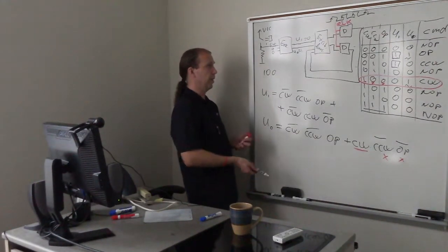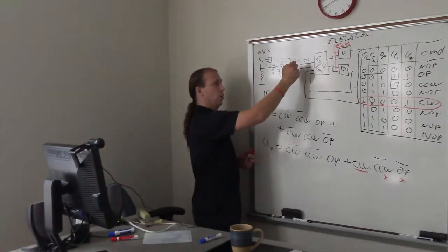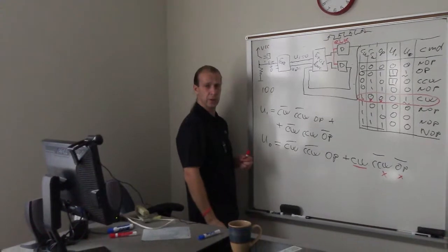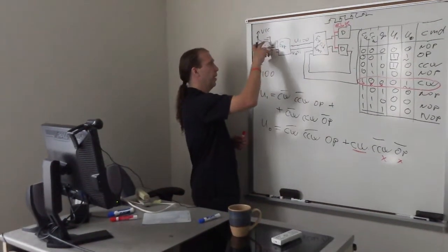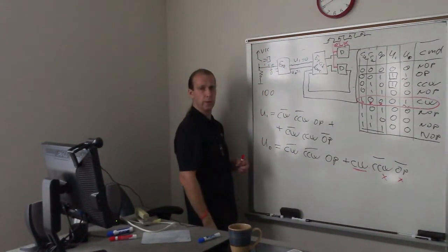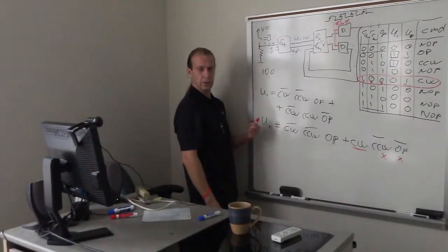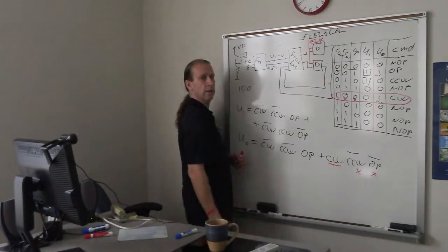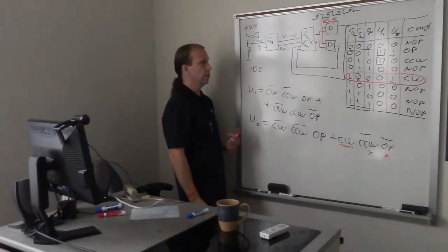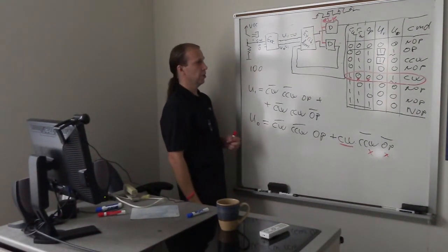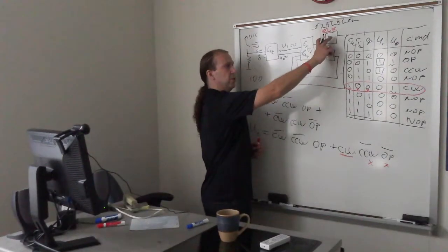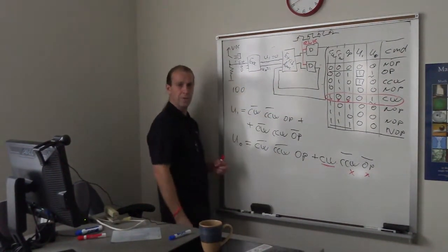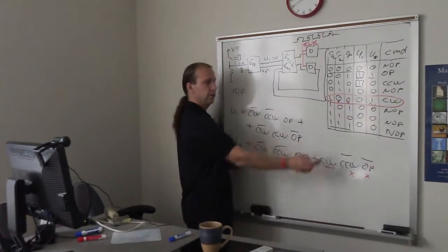And the problem is that this combination 0, 1 will stay at the input of the excitation function as long as we continue pressing the push button. During this amount of time, many clock cycles will come in, which will change the state of these two triggers, actually responding to the command CW.